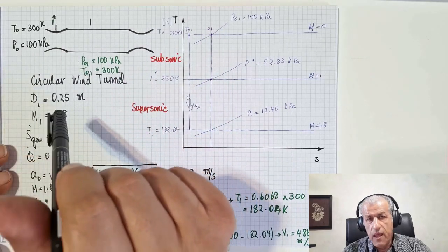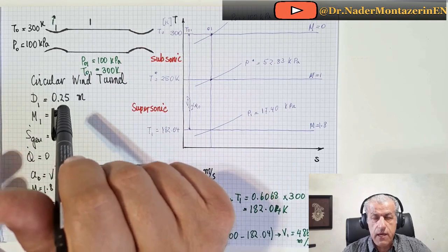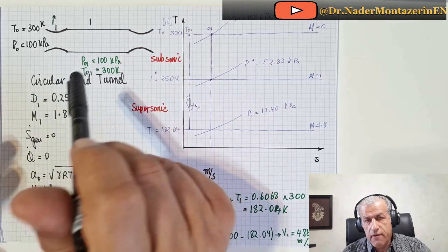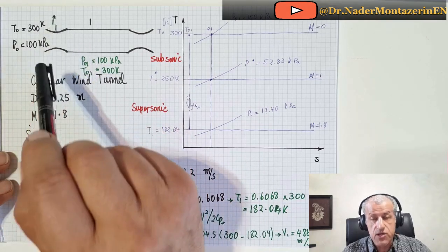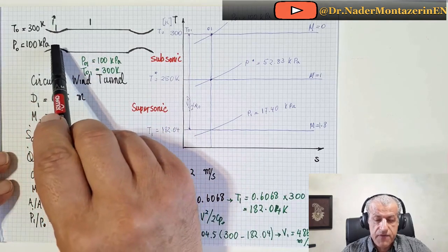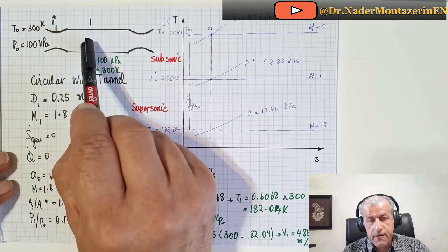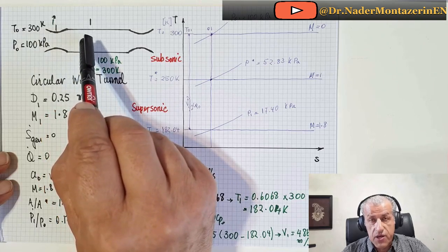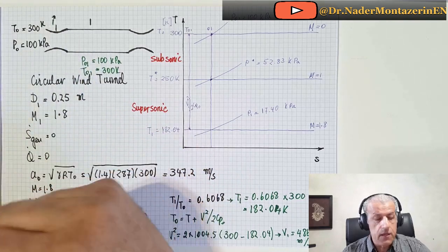But as you know from the shock wave theory and the shock wave in the diverging section of a converging diverging nozzle, after the throat reaches Mach 1, by any further reduction of the pressure downstream, there would be a shock wave after the throat.